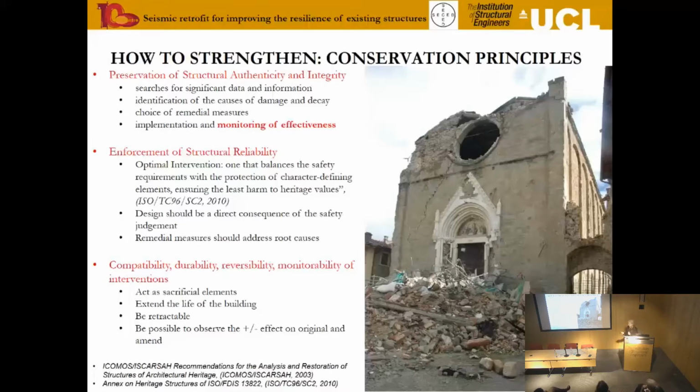So when designing new measures, a remedial measure, we should try for these to act as sacrificial elements, i.e. whatever strengthening we put in, it should help the building to act as a whole, but it should be the first to damage, so as not to damage the historical fabric. It should extend the life of the building, so start thinking about what it is that we are doing and for how long. Be retractable, i.e.